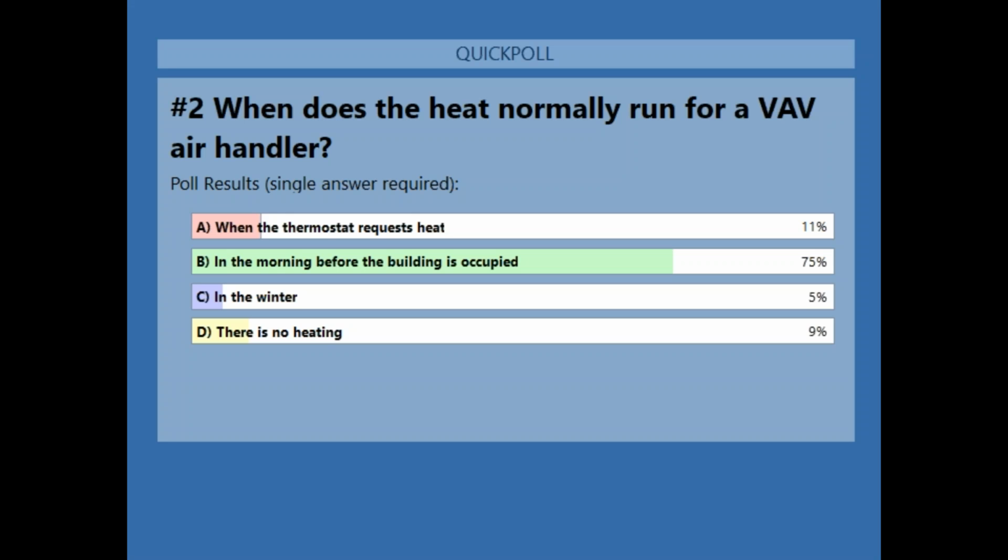So in those cases, we could buy a rooftop unit with staged gas heat, and we do what's called tempering mode, and we put some extra sensors in the duct system so we could temper the air back up to 55 degrees like Ben is describing. I could also do the same thing with an air handler that had a hot water valve if I wanted to. I could add that sequencing in. But a normal traditional VAV system would not have any ability to temper the air back to 55. So Ben does have a good point.